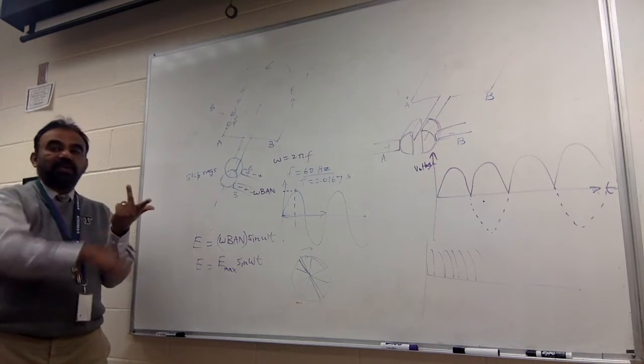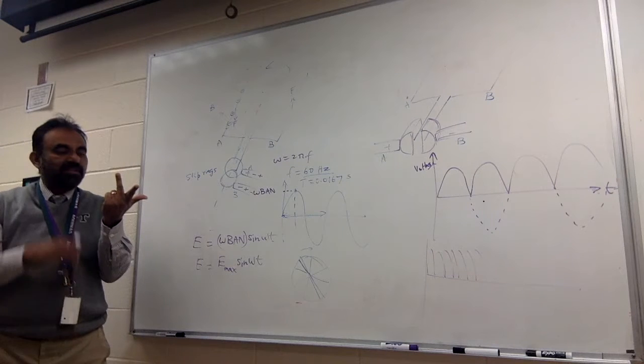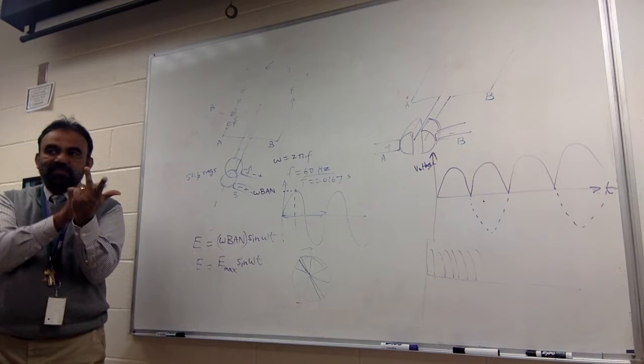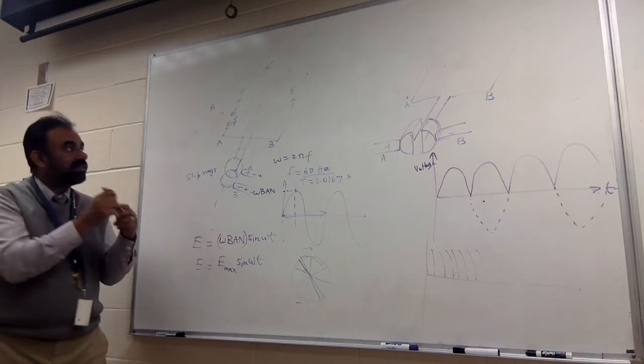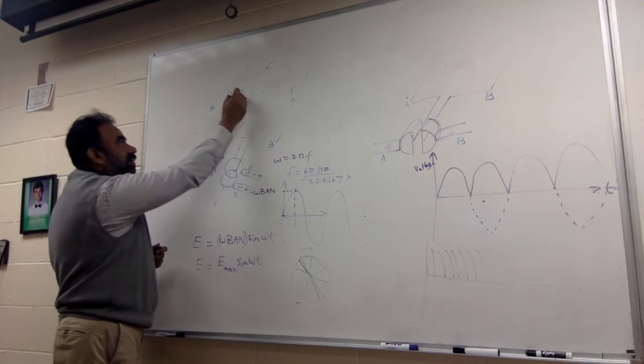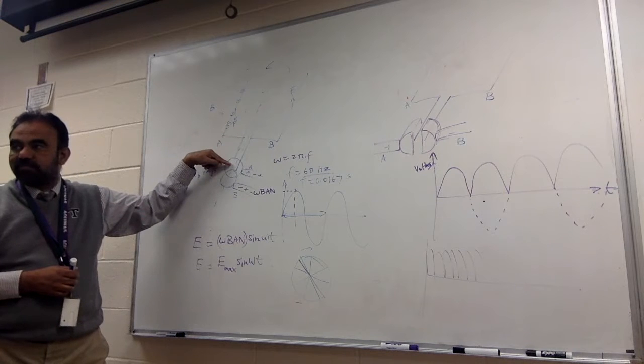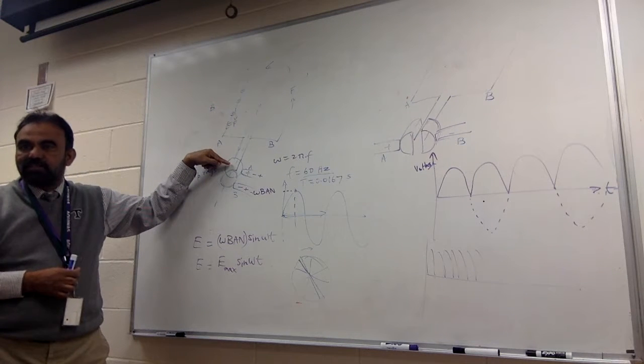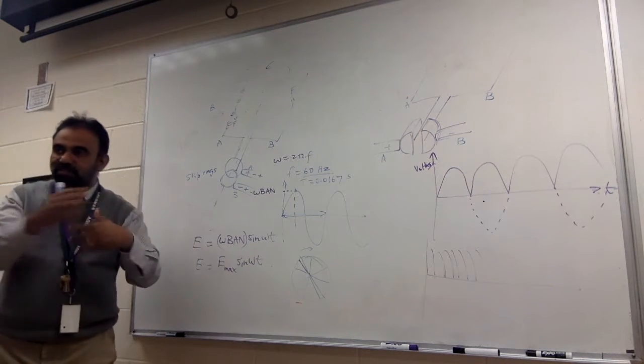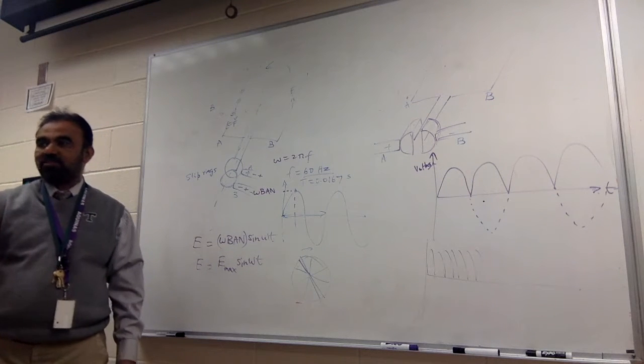And magnetic field is that way, using Fleming's left-hand rule. So which way are the electrons going to be drifting? Inward. So the electrons are going to go this way. That will create a current which way? That way. You get it? So the induced current is as a result of all these processes, but to make things easier, we just use Fleming's right hand.